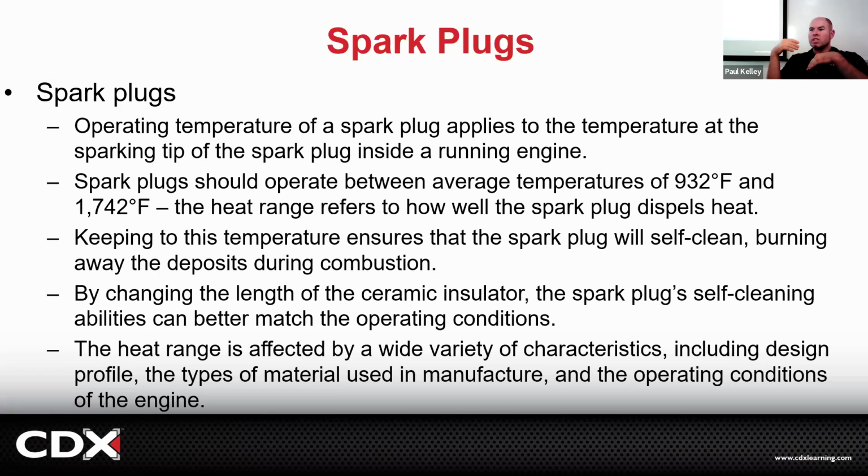But if you keep throwing hard wood in there, like wood that's dried up, like oak or something, it'll get really hot and it'll incinerate all that darkness off the glass. That's self-cleaning. These self-clean too. But if they run too cold, they'll stay dirty. If they run too hot, they'll actually prematurely wear, and they could cause overheating. You could even see spark plugs melt down. But if you keep them right in a good range, they'll self-clean, they'll burn away the deposits, but they won't necessarily prematurely fail. So the engineers figured all that out. That's again why I'm saying run the original.